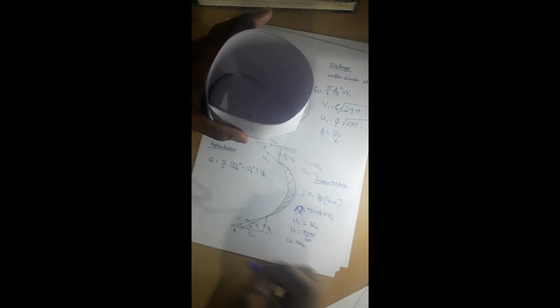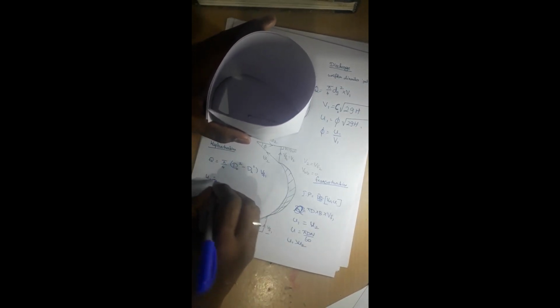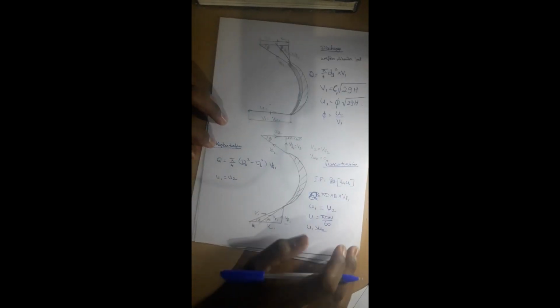and here the velocity at the instant will be given. The water is flowing from top to bottom, so diameter is playing a minor role here. So velocity at the point at the top here will be equal to the point here. So V is the same, so V1 is there. So velocity u1 will be equal to u2. So based on these assumptions, we can solve any kind of turbine problem with these same formulas. Only thing we have to know is the equations here.